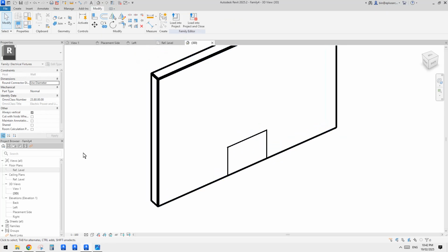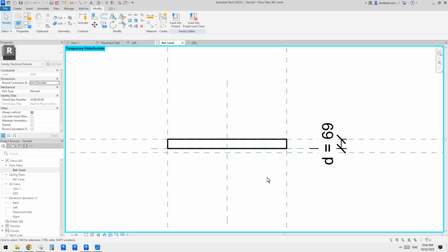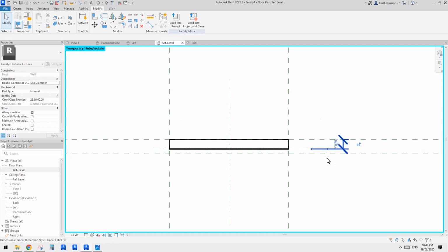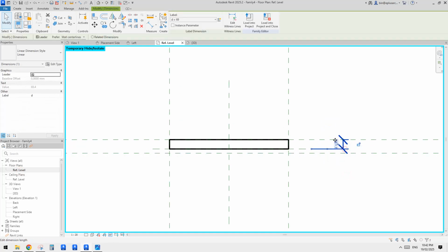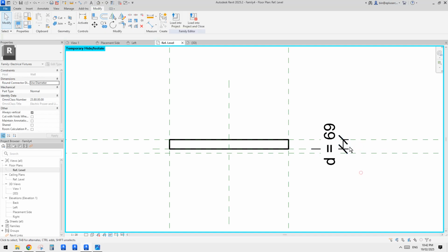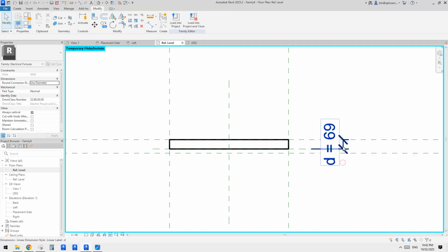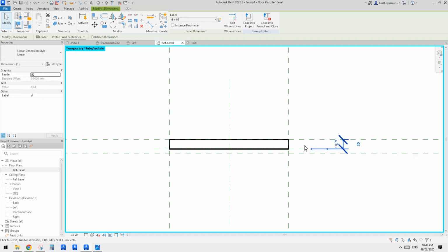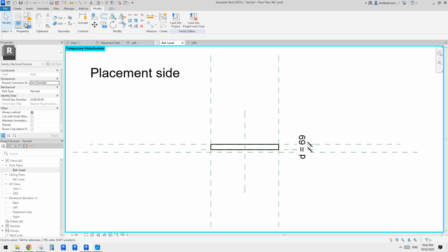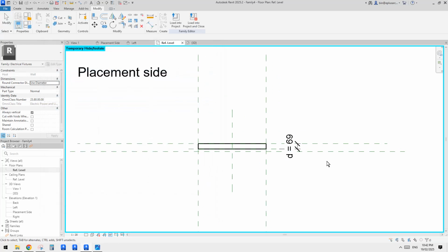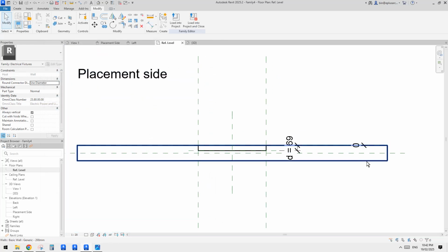So what we need to do is go back to floor plan. We just need to select this dimension or this parameter. So click on this. So by locking this one, actually, let me just, so create or remove a length or alignment constraint. So it doesn't mean this dimension can't be changed. It only means when we change the wall thickness, we need to type HR to bring the wall back.